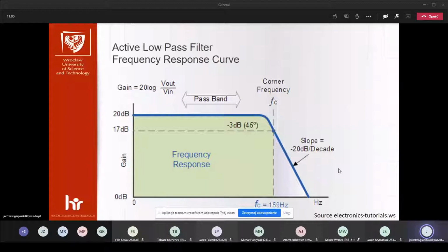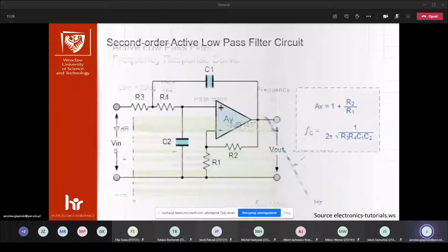So this is the typical situation of a filter made of resistor, capacitor, and buffer. This is usable, but if we use the properties of the amplifier, high input impedance and low output impedance, we can make a more complicated situation.